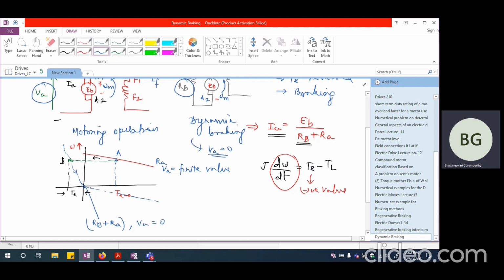So if I want to have a good amount of torque all the time, maybe I have to reduce the resistance. Let me draw this. If I reduce the resistance, I should have another characteristic like this, and another like this. As I decrease the resistance, the steepness of the characteristics decreases further and further. Originally, it was quite steep. You can see that this was very steep. Now this has become less and less steep.